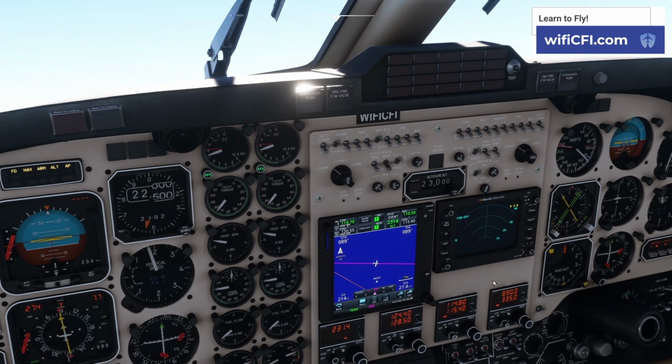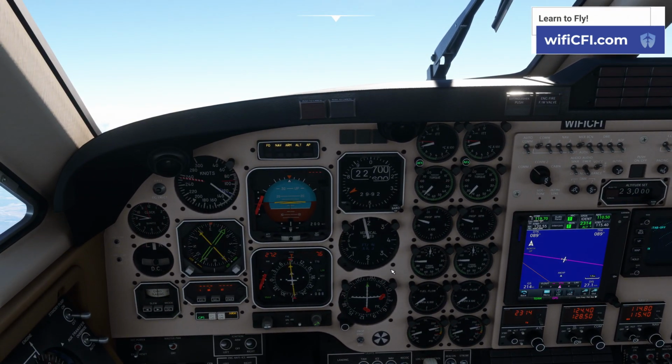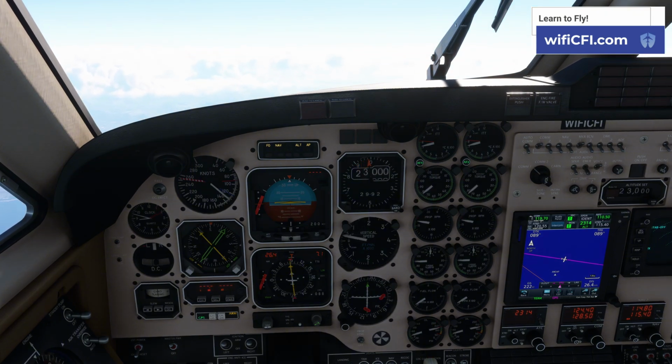Alright, it looks like it's good out ahead of us, so we're just going to leave it like that. Coming up on our cruise altitude, we'll do our cruise check. And then cruise power is going to be set. We're going to get our props back to 1700 RPM for cruising. Torques and temps are looking okay. Maybe add even some power and I think we'll be alright.